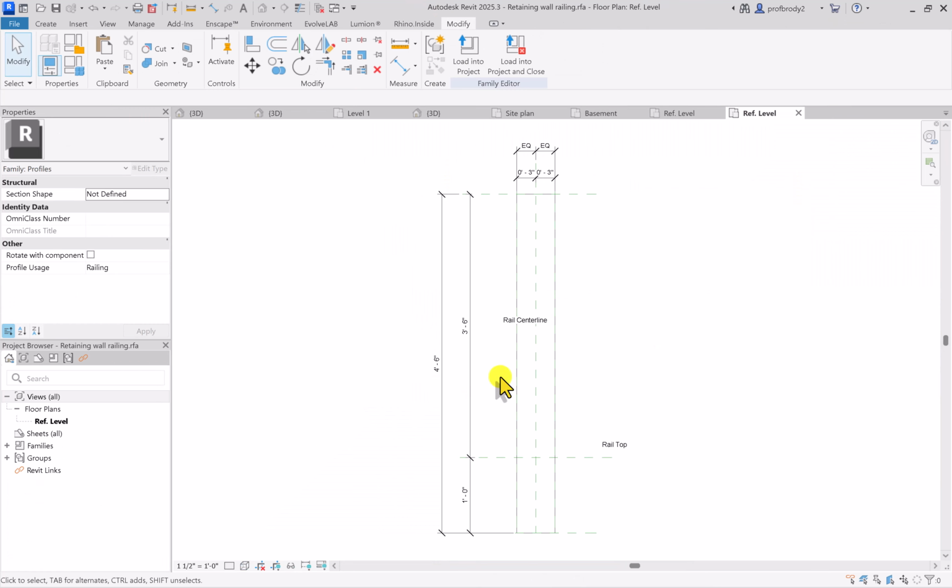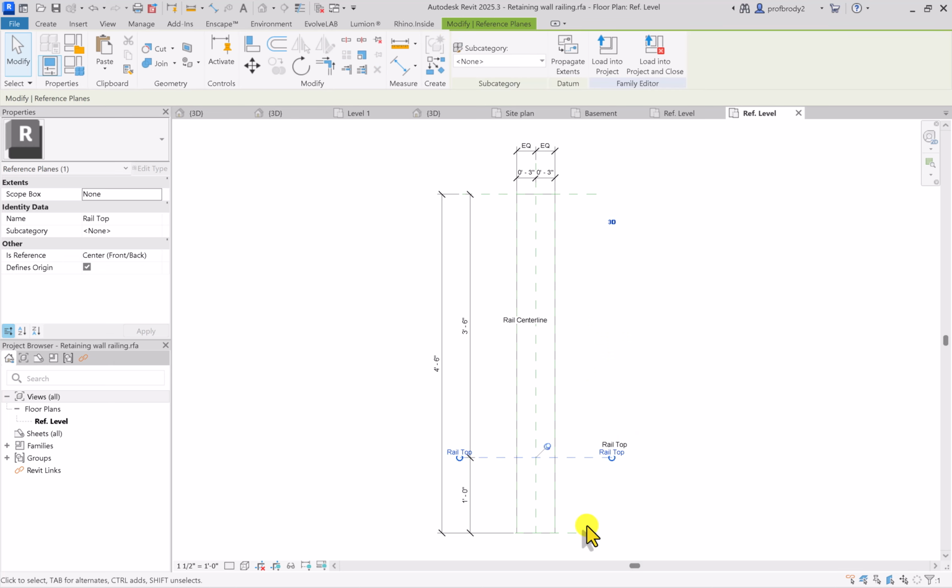And so the main wall, the kind of thickened part, you can see there's a top and a bottom of the rail that's below kind of the reference line. In fact, I've made it go down 1 foot below the reference line just so that we have some thickness underground. And you can change the offset in Revit once the railing is placed. But anyway, the height above the ground is about 3'6", and it's centered on whatever reference line you draw. And of course, you can move that left or right if you want it to be all inside, if you don't want any kind of dirt leaking into the wall. But let's just stick with it this way so we don't have to worry about the direction of the wall.